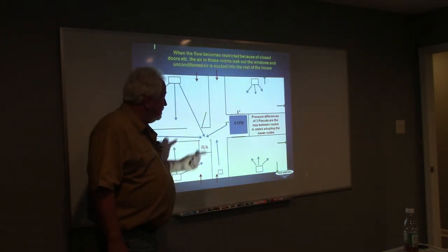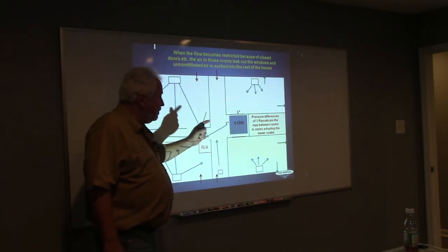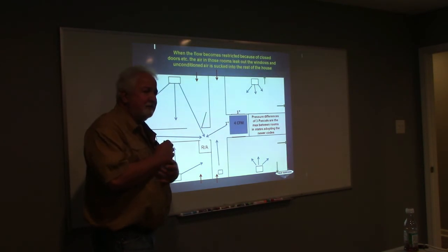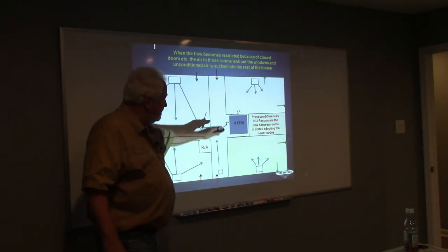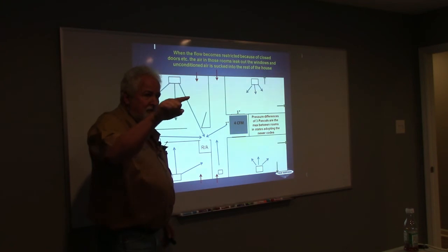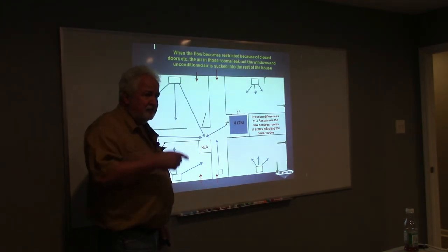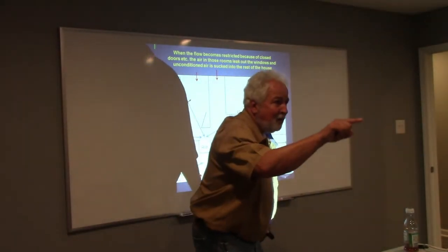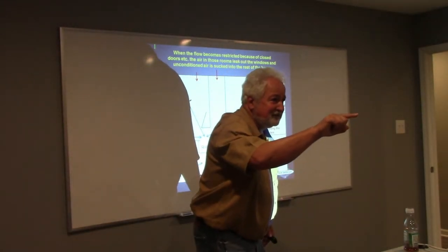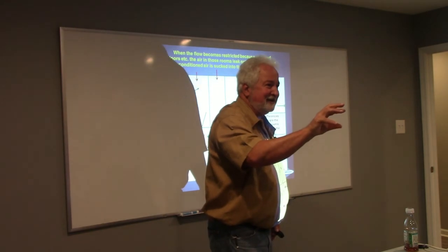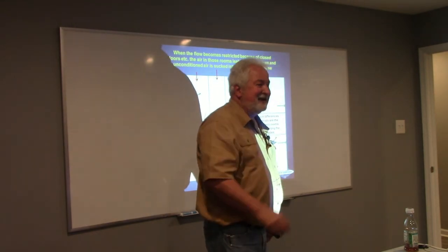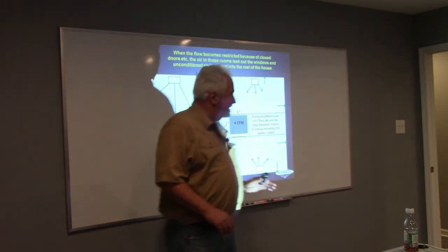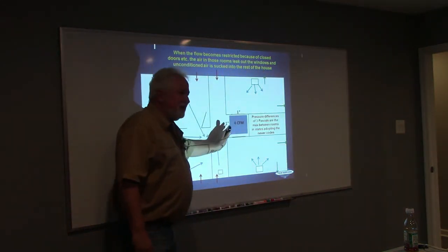So, remember that 1 inch off the bottom of the door? Look, real quick and easy before you have to break out your CVA, for every 1 inch you cut off the bottom of that door, you're going to move 4 CFM out of there. Look, Mike, I'm going to make it easy for you to remember. 1, 2, 3, 4 CFM for every square inch. You got that in your head? So 4 CFM for every square inch.